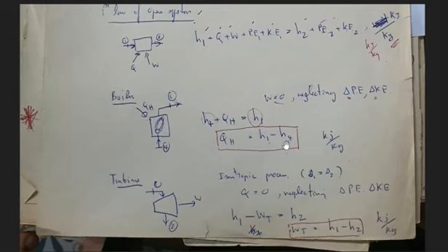We can determine the entropy coming in at point 4. Then we would know how to calculate the amount of heat that we have to put in the boiler. Again, the unit would be kilojoule per kilogram.